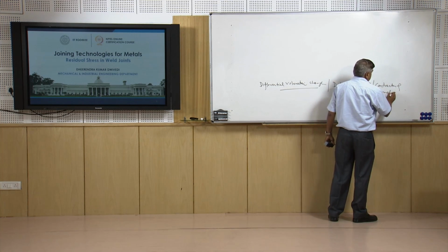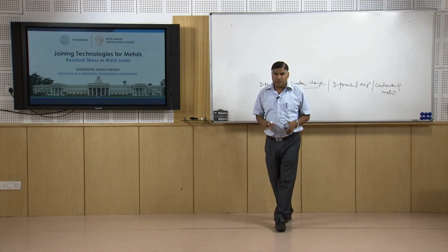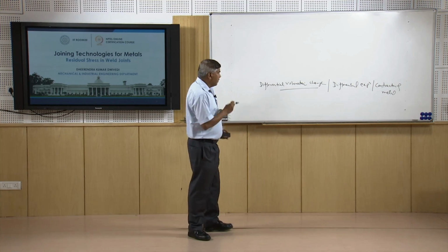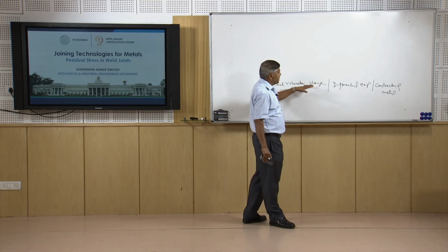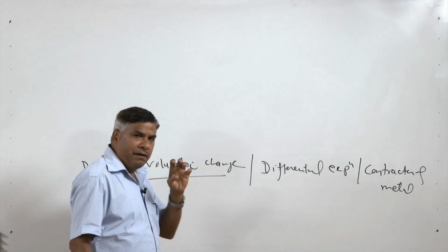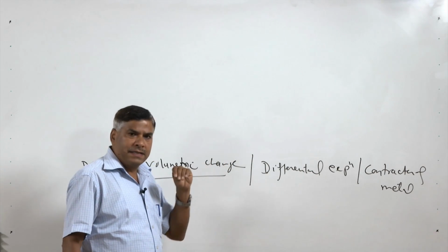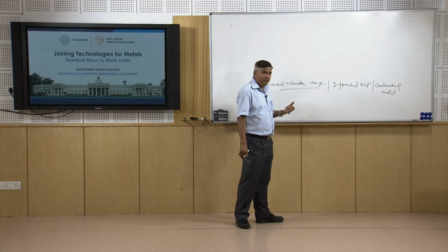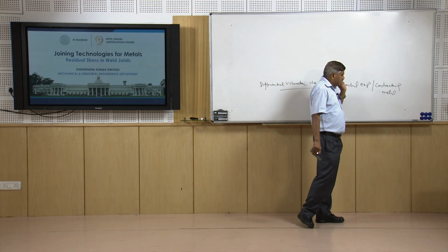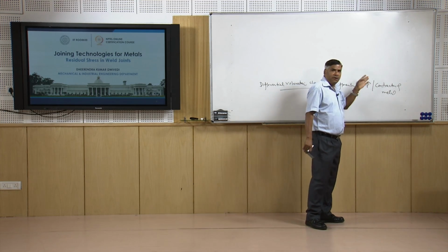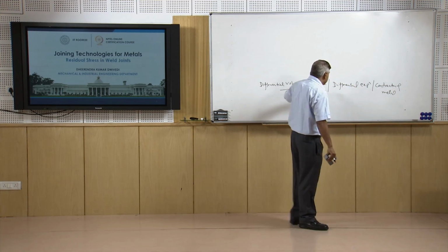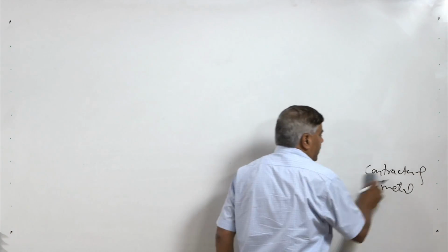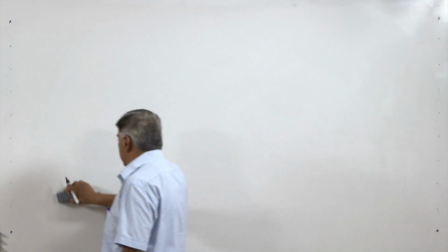of metal. Whether it is machining or heat treatment or welding or any other process, wherever there is a differential change in the volume of the metal, meaning one region is expanding, another region is expanding less, one region is contracting, another region is not contracting by the same amount, or the expansion is different in the different zones, or the contraction is also different in the different zones. These situations in turn lead to the development of residual stresses, but how, that is what we will be seeing.